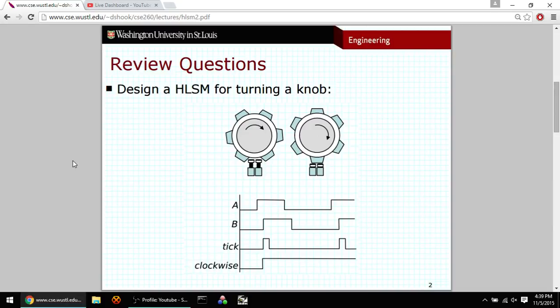We just need more complicated transitions. Yeah, we could. Some type of variable. We could include some more stuff on these transitions. It's a trade-off, though, right? I don't like my transitions to be crazy complicated, because then what's the point of having a high-level state machine if I just make everything in 2 states and write a whole chunk of VHDL code for each transition? That's kind of defeating the purpose a little bit. But I agree, we could certainly do that. That is an option.